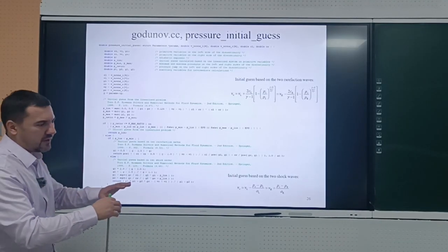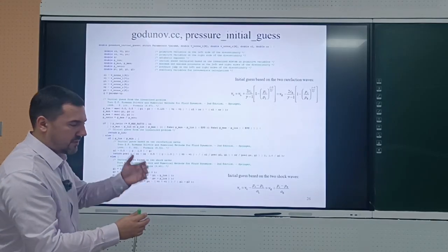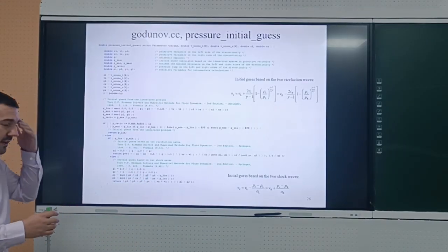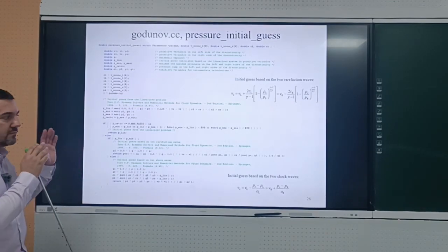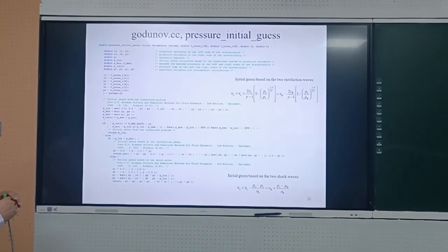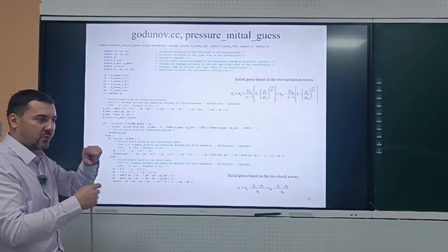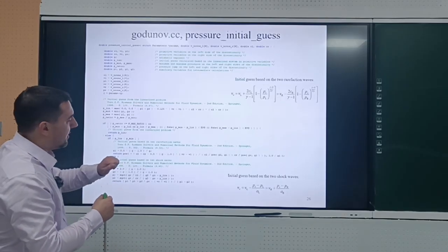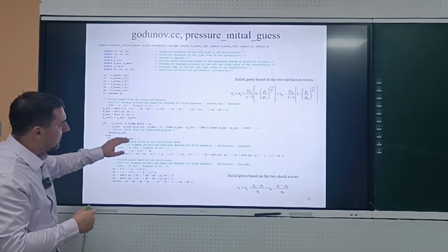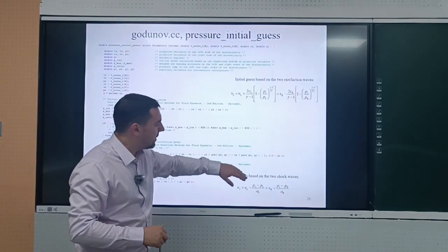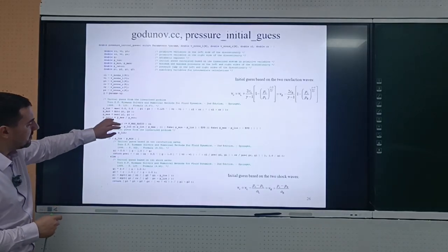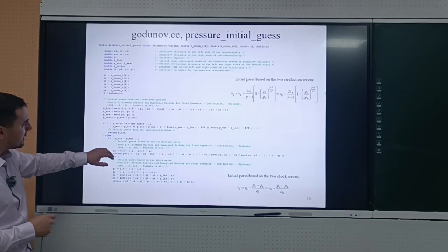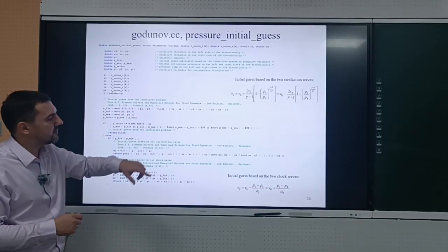So there is no unique procedure for how to do that, as for any nonlinear equations that you would like to solve. He analyzed the initial gap in pressures to the left and to the right: if it's too big, he used the analytics for so-called two rarefaction waves or two shock waves. If the initial gap is small enough, the linear approximation can be used for the initial guess. But what does it mean, initial guess for two rarefaction waves or two shock waves?